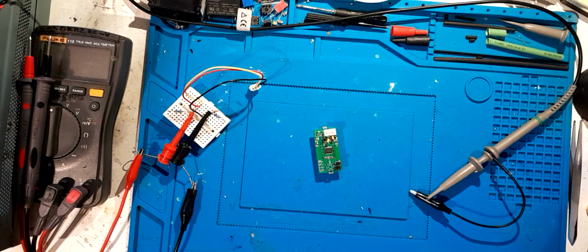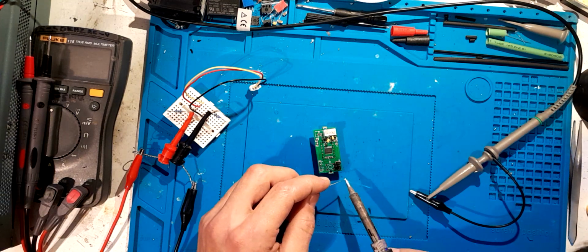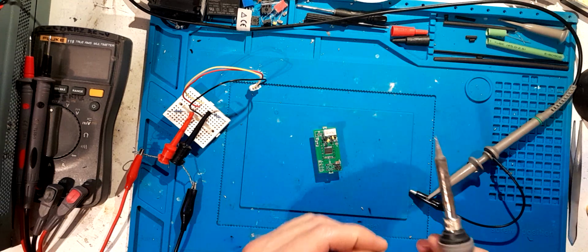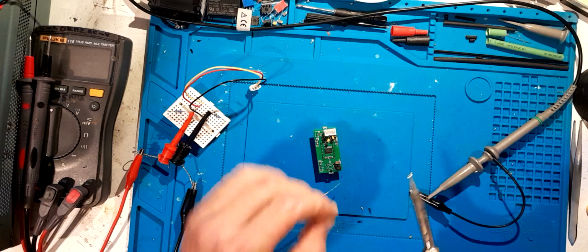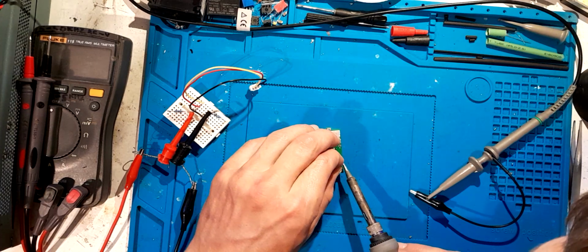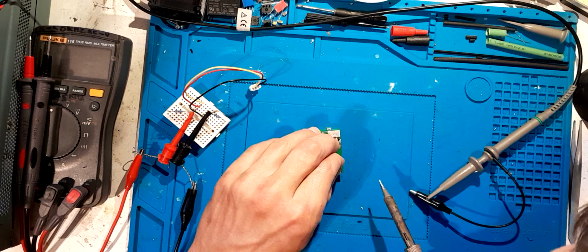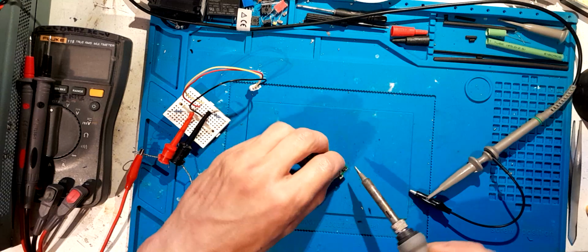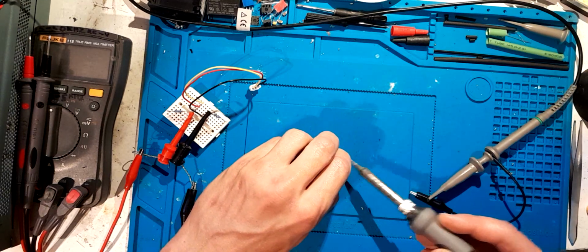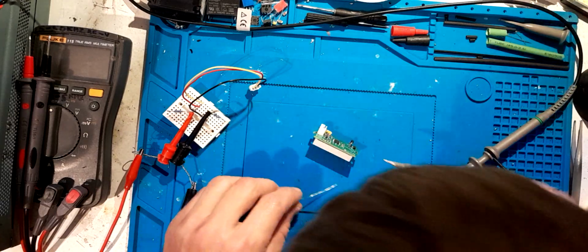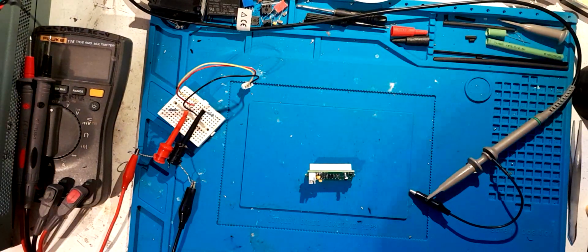Okay. This is the diode I was talking about that will stop any over voltage on power down from the bigger capacitor on the output side from coming over to the input side and damaging the regulator. Okay.